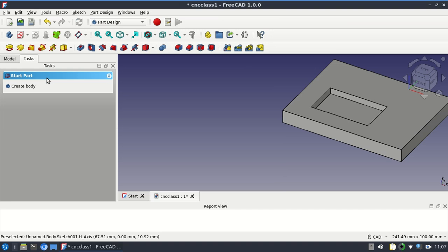The only thing that I want you guys to have is the thickness of your block here. This is the only important thing. Why is this important? Because if this is actually less than the thickness of this, you won't cut through.